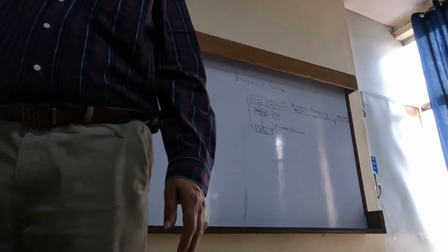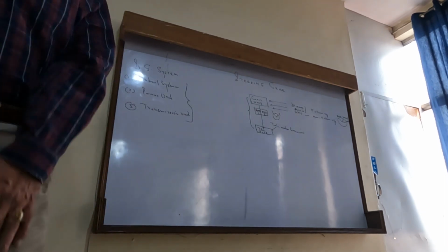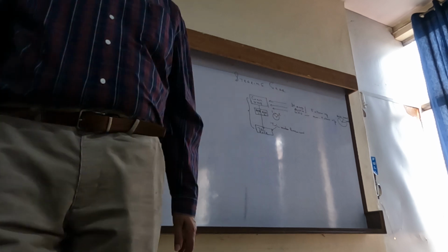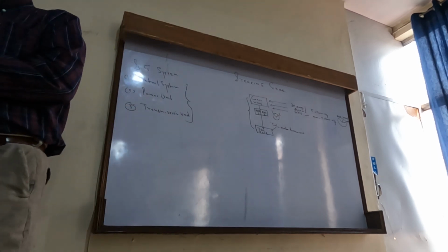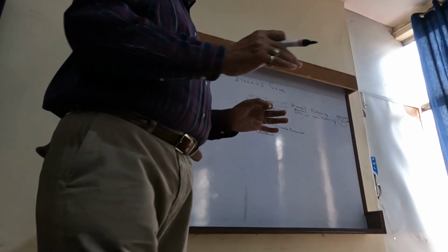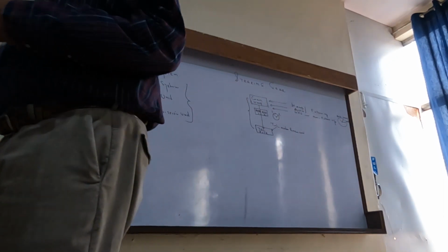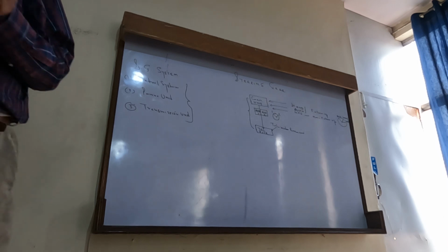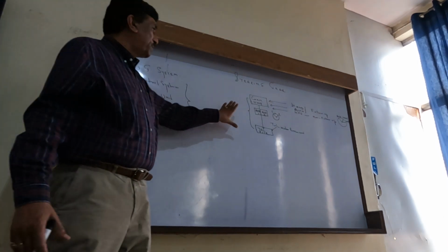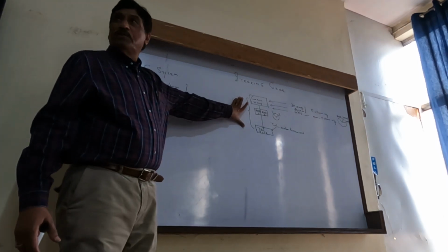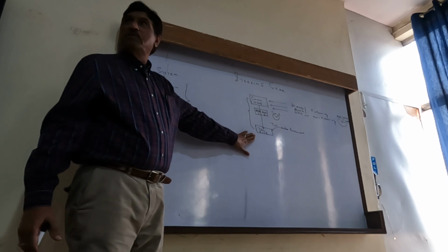Telemotor system. And we have to keep this in mind. Why? Because in your exam, sometimes A part asks you to sketch and describe a four-ram steering gear. B part, in case of telemotor failure, what you do. So immediately you should understand what is telemotor. The telemotor part is only this much: transmission from the bridge and receiving the signal.